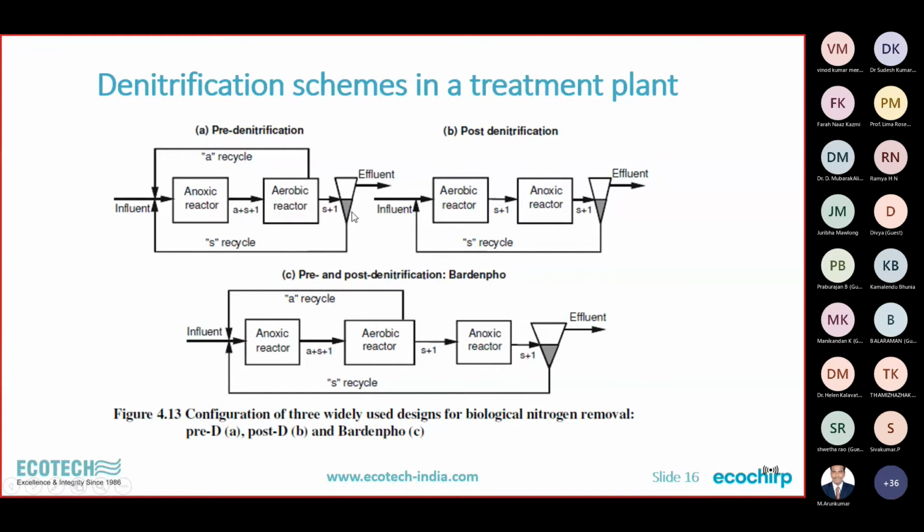And also the standard recycled activated sludge, RAS sludge from the settling tank also comes to the anoxic reactor. So the anoxic reactor has a mix of all these kinds of bacteria. The carbon-eating bacteria, the nitrifying bacteria, the denitrifying bacteria, Nitrosomonas, Nitrobacter, all of them are present.